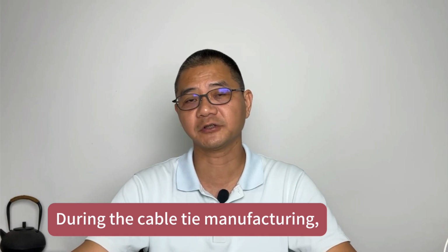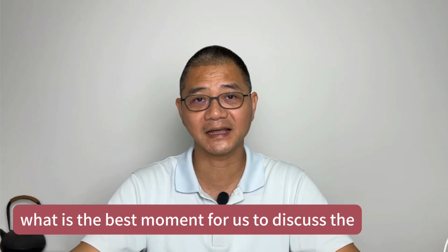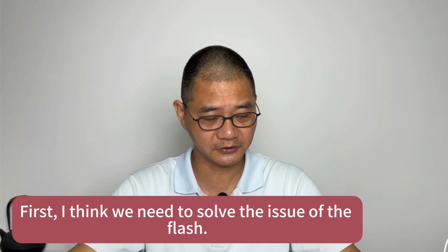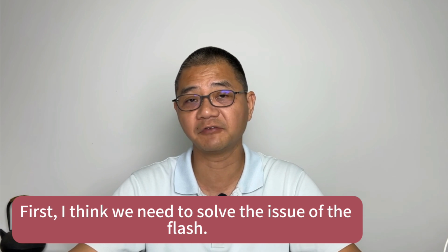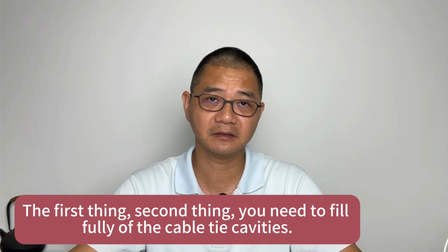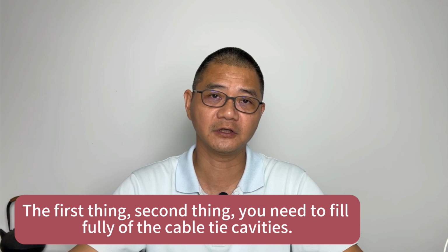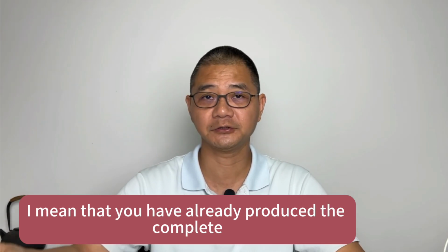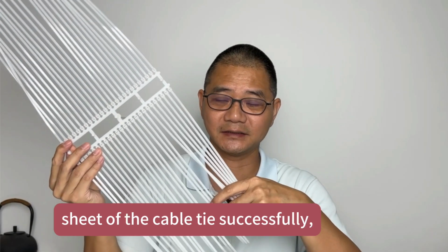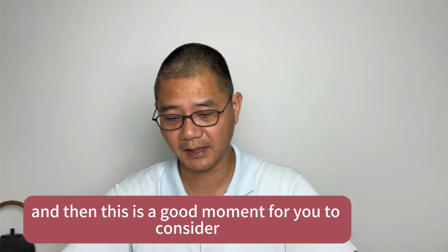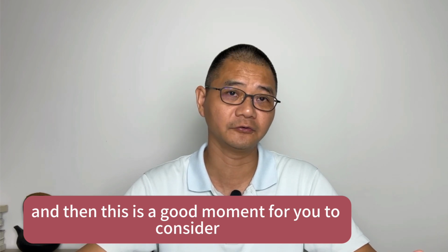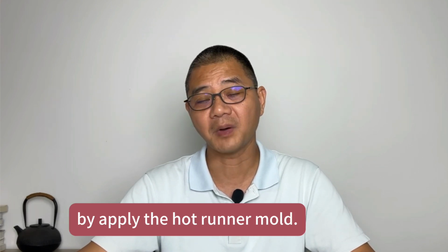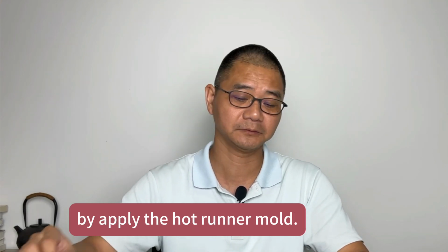During cable tie manufacturing, what is the best moment for us to adopt the hot runner or cold runner mold for the cable tie? First, I think we need to solve the issue of the threads. Second, you need to fill the cable tie cavities fully. I mean that you have already produced the complete sheet of the cable tie successfully, and then this is the good moment for you to consider whether you need to improve your production by applying the hot runner mold.